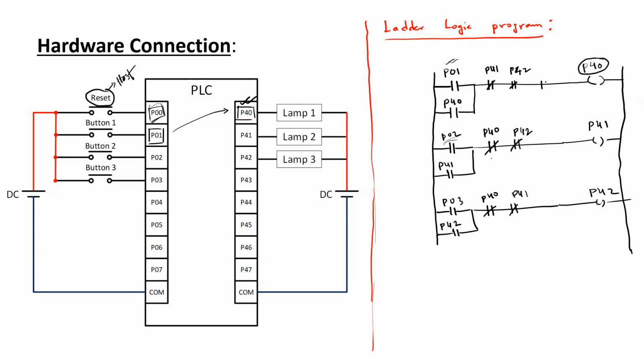Okay, so yes, that could be one possible option. Connecting normally closed contacts in all the 3 different lines associated with the port address P00, so that when the button on P00 is pressed, these contacts become open and de-energize all the output coils and take the entire system into its initial state. Now, this option is definitely going to work.